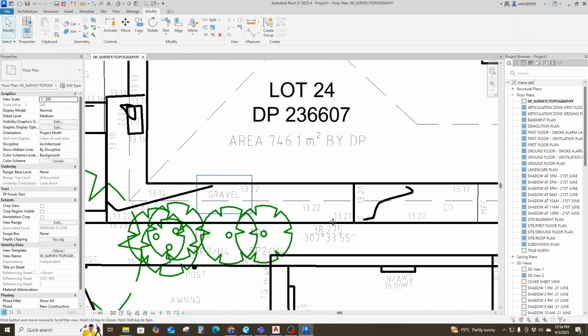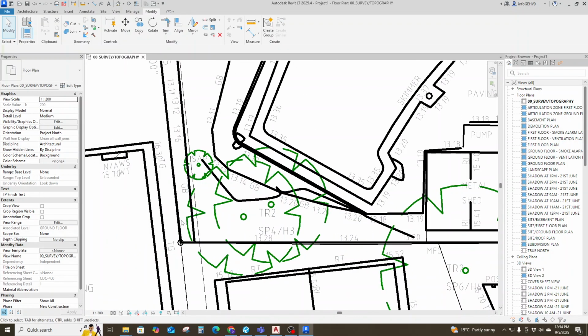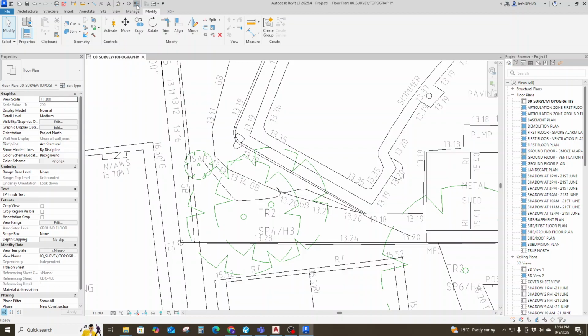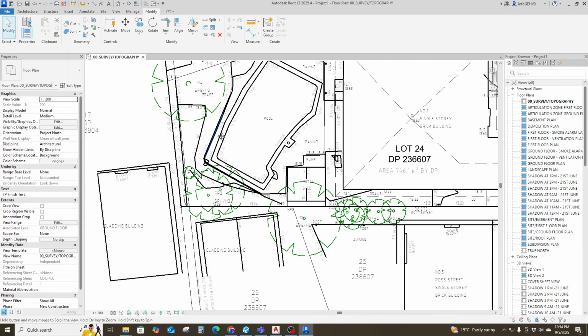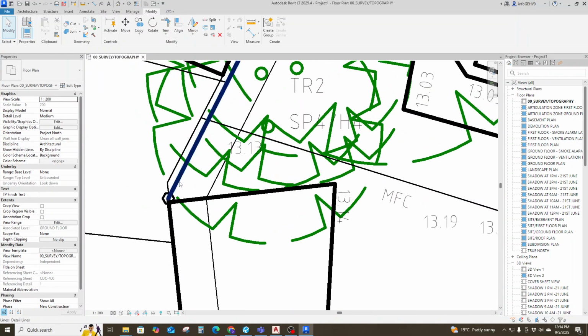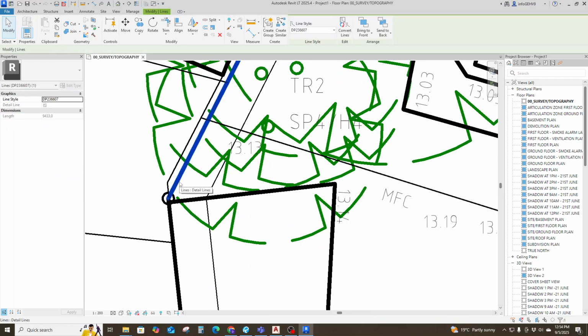Okay, so this fence line is deleted from here. Now let's go here and select this. Let's see what this is. This is also fence. Okay, the line weight right now is thick, that's why you can see that, and you can change it to thin as well. But this is what it's going to be printed. So you can keep on tabbing which one is good for you.